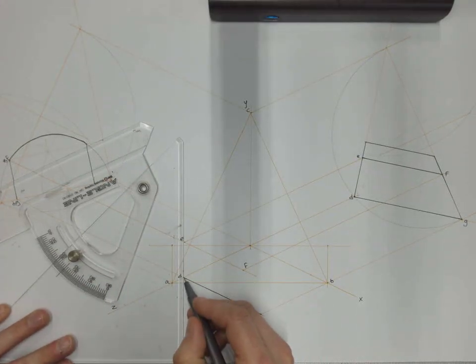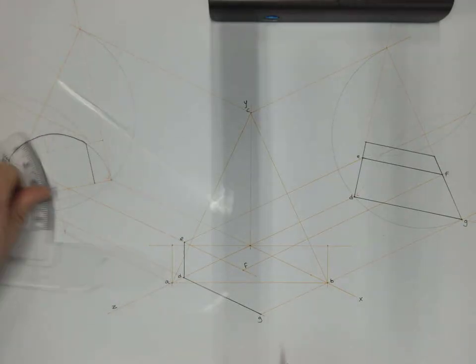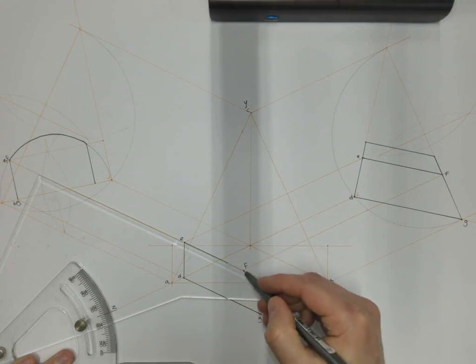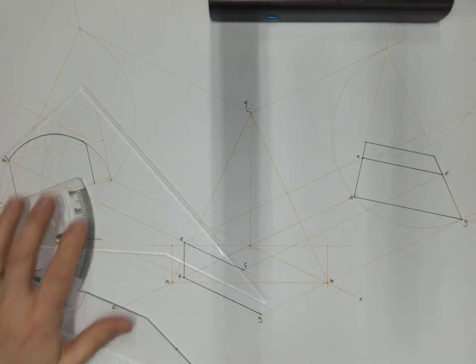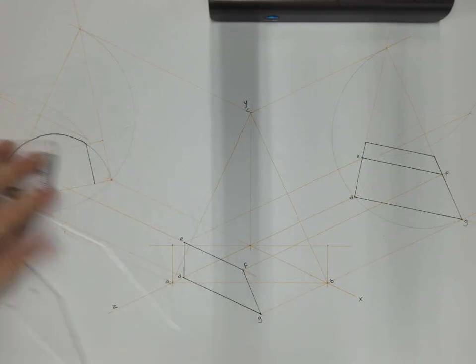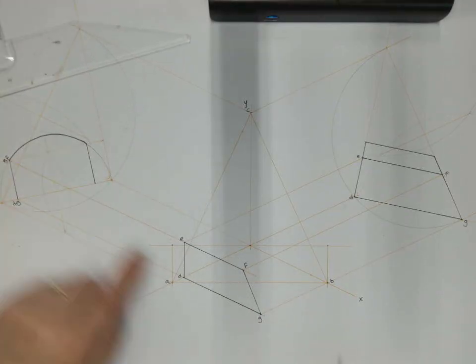If your drawing is accurate, D and E should be vertically above one another. E to F should be at that axis. Well, of course it is. It should be parallel to the x-axis. And now you also have the angle F to G. So that's the first visible surface of this axonometric projection.